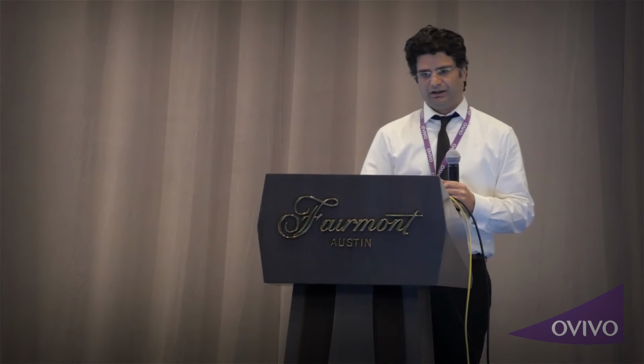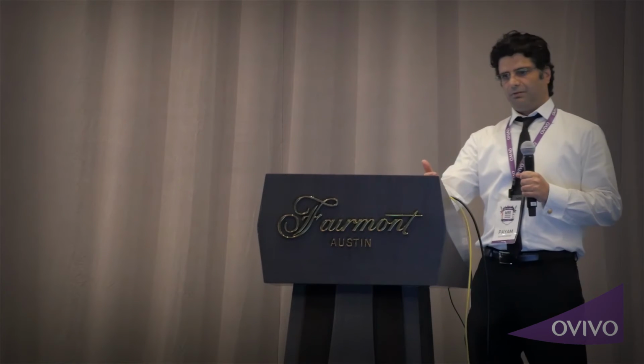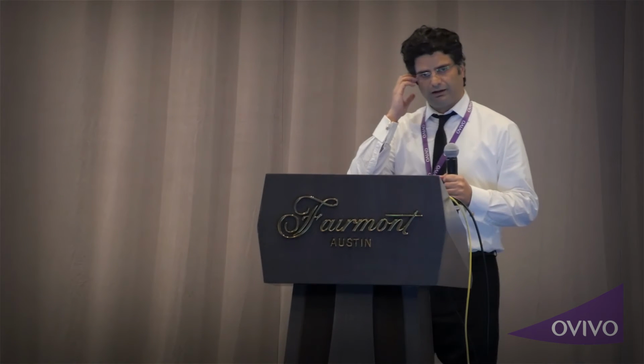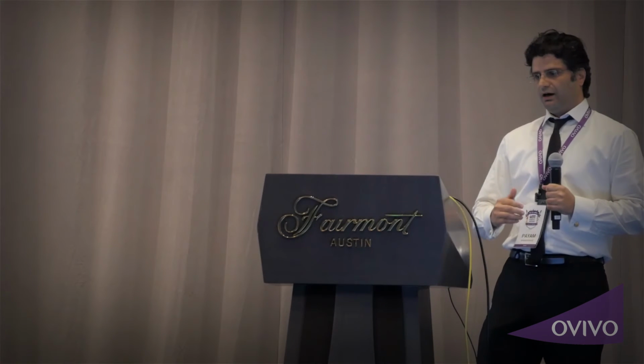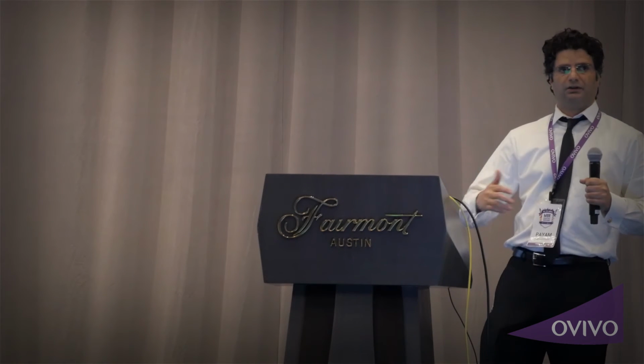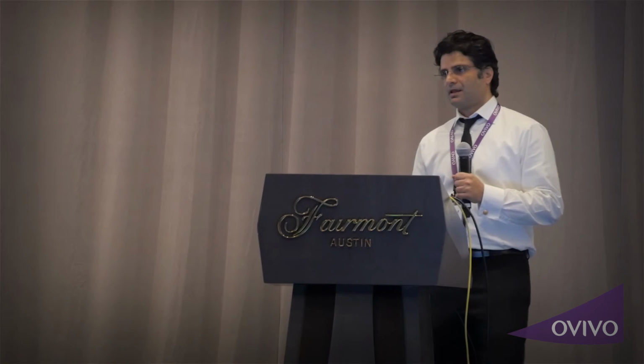So field observation again. And the solution to that: we collected all the data from the field and from the online available historic data, and we modeled the system based on the new values. And we were able to establish a roadmap to optimize the system with the new parameters and make field adjustments. One simple field adjustment we made was to the pre-aeration blower, or MBR blower.